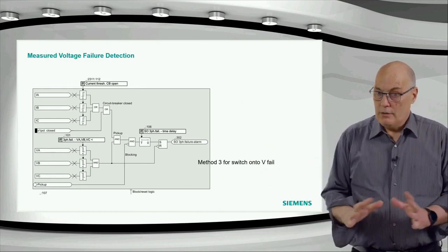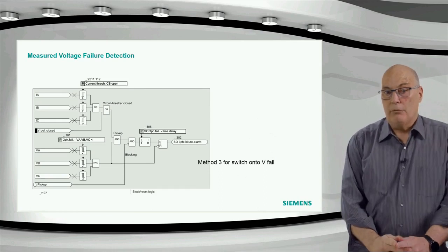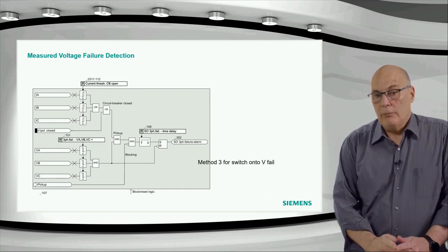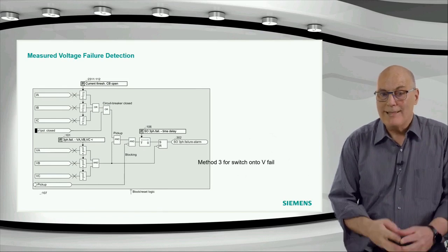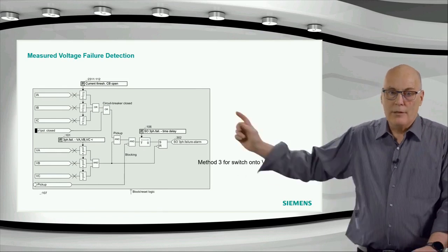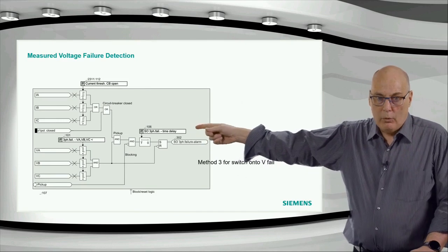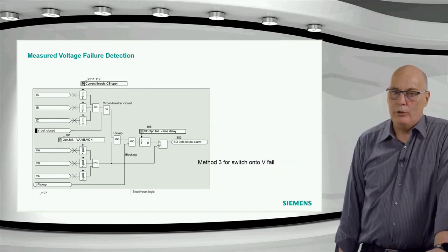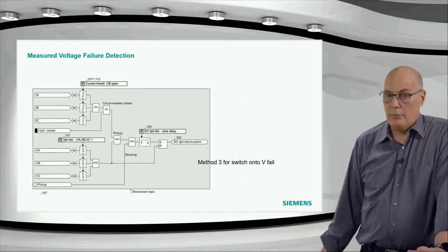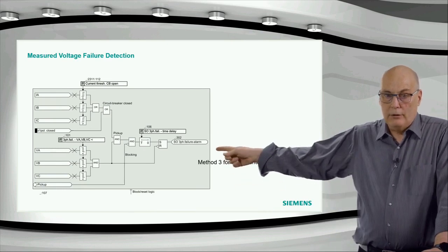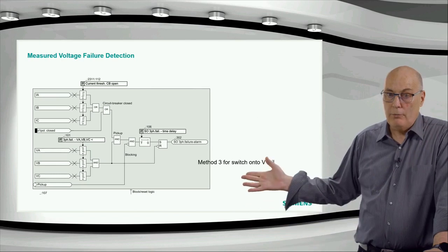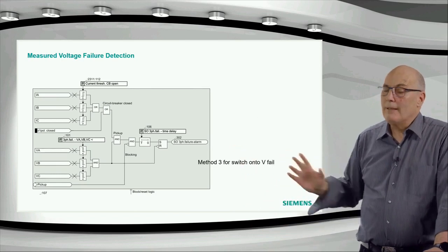And then the last one, as I said, the switch-on one, is the unusual one. It is time delayed. You may see this sometimes if you have a relay and you simulate the circuit breaker auxiliary contacts to be closed and there's no voltage connected. You can see the one pole open or one pole closed condition will be true. Greater than one pole closed, typically 3 pole closed is true, and you have no voltage. Okay, so at the bottom you see no voltage and 3 pole closed.